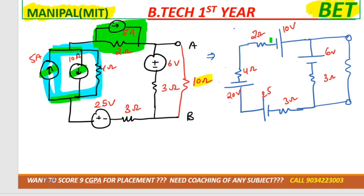Okay, after solving this one and this one, we will get this value. Now you can see that 2 ohm, 4 ohm and 3 ohm, they all are connected in series, right? So if we combine them, it will be 9 ohm. Now we have to check for the battery.